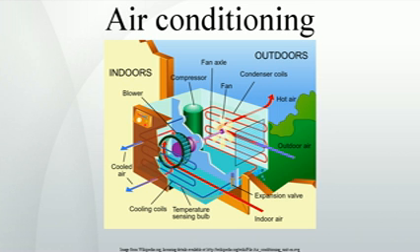SEER is unusual in that it is composed of an imperial unit divided by an SI unit. The COP is a ratio with the same metric units of energy, joules, in both the numerator and denominator. They cancel out, leaving a dimensionless quantity. Formulas for the approximate conversion between SEER and EER or COP are available from the Pacific Gas and Electric Company. From equation 2, above, a SEER of 13 is equivalent to a COP of 3.43, which means that 3.43 units of heat energy are pumped per unit of work energy.